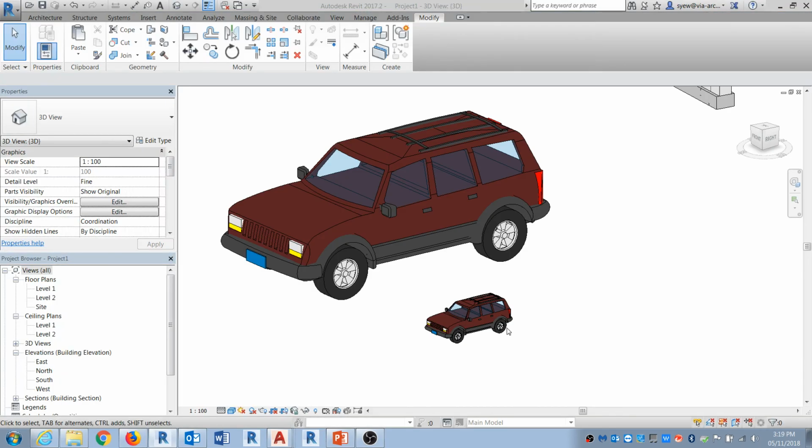This is probably the easiest. So all you have to do is just get one family, and then you just put it into planting, the first planting. Make sure it has a way to flex. Next thing you do is dump that into the next planting family, and then you link the first family height with the second family. Once you've done that, fingers crossed, it works, and then you can try scaling it.